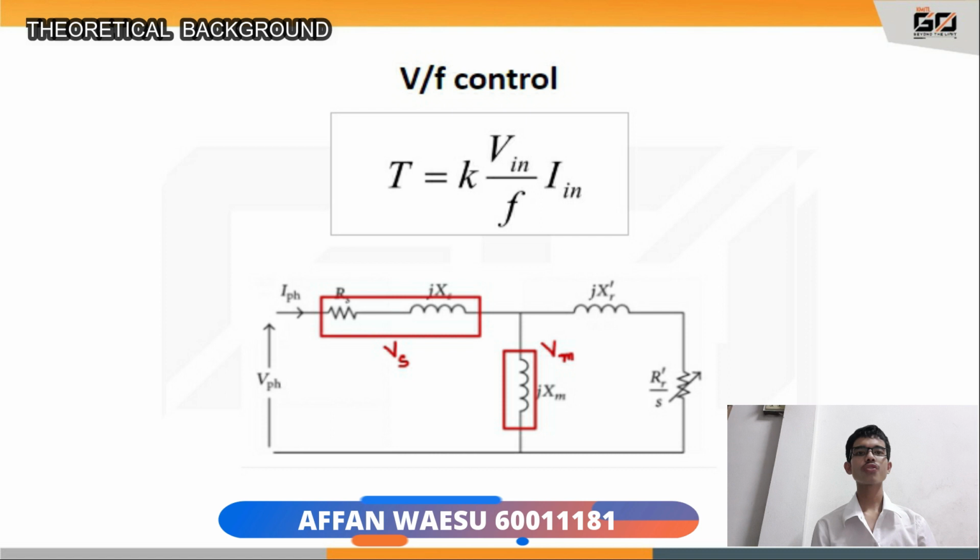Motor control through frequency control has an impact. When controlling at low frequencies, the motor cannot create a magnetic field due to the resistance of the stator coil. The voltage on the air gap is very low. V/F cannot be used to create a magnetic field. Therefore, the voltage is compensated during the start, called the voltage boost, so that the motor can create a magnetic field during the start and maintain a constant magnetic field.